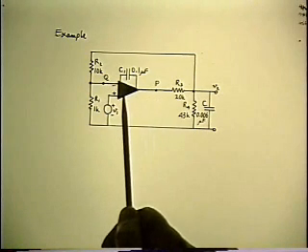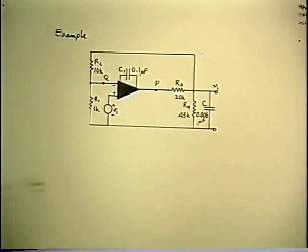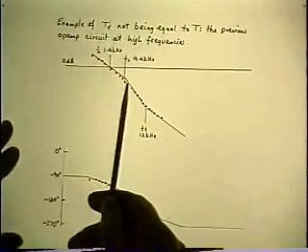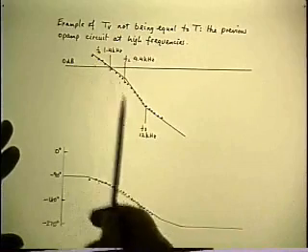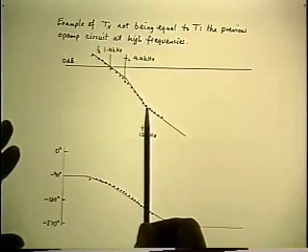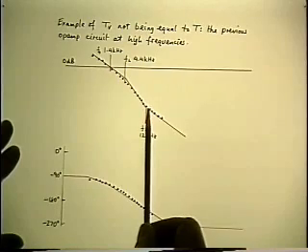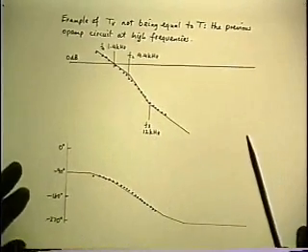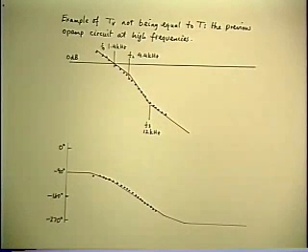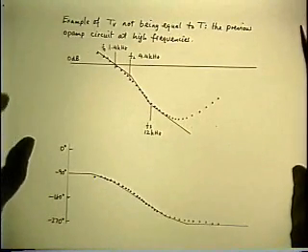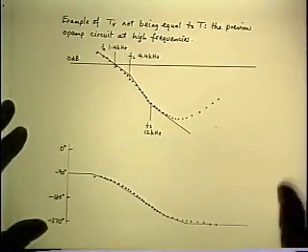Here's the circuit. We chose P as the injection point. We predicted a loop gain that had 2 poles. And then we made measurements, and we discovered that there was a right half plane 0. And then we found out where that came from, and we're satisfied with that and say, well, fine, everything's all right. Unfortunately, if you simply continue the measurements up to higher frequencies, everything is not all right again.